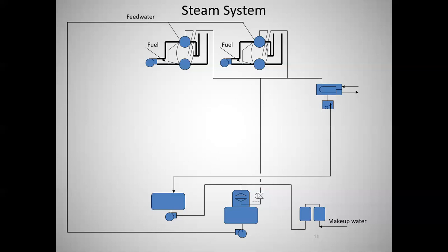And then you would have a level over here, and say you have to continue to feed the boiler. But if I'm not getting enough back here and I continue to feed the boiler, then the level in this tank will start going down. In which case that would open a valve, and this would probably really get put in over here, and then this would flow up together. But that's just not the way that diagram happened. Absolutely.